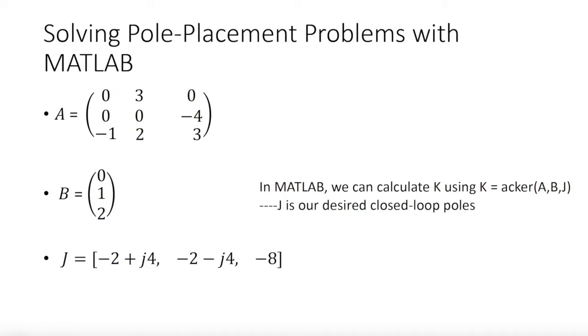For the next part, we are going to go through pole placement. Consider the system x dot equals A times x plus Bu, and the system has some eigenvalues that can be computed easily. Then if the system is controllable, it means that we can put the eigenvalues of the closed loop system anywhere that we want by using a state feedback control.